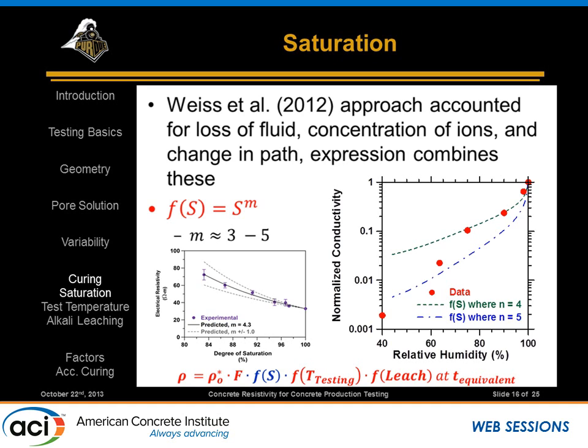All right, so if you looked at this, here's the actual data to show you this particular test was around 3.4. This is the conductivity measured from a completely separate set of experiments where we were looking at drying. And here you can notice that this is a log scale. We see an enormous change in the conductivity or the resistivity that can be completely described by this model until you get to a point of about 50 or 60% relative humidity. And the reason that it stops to work really well at 50 or 60% relative humidity is mainly because the pores dry out at that point, the capillary pores are almost empty, and almost all the conduction is happening through the gel pores in the overall system.